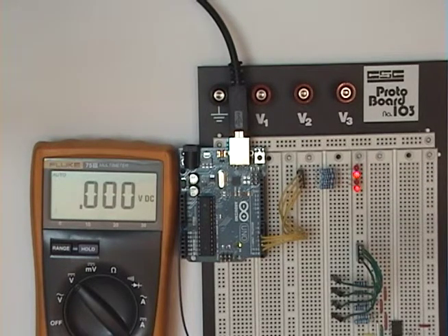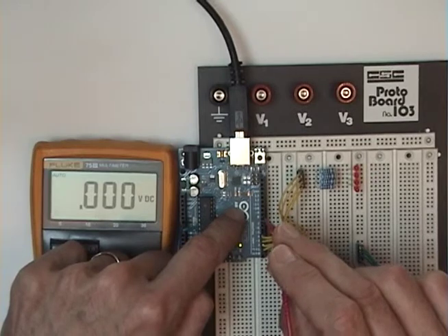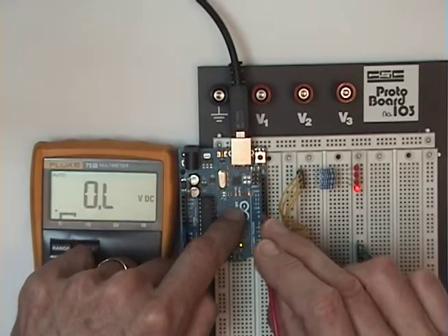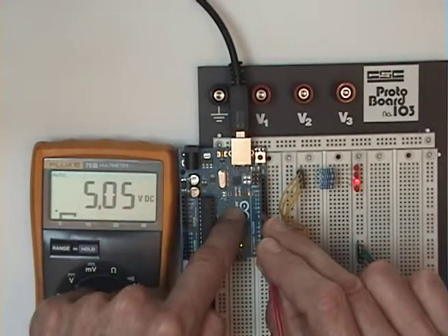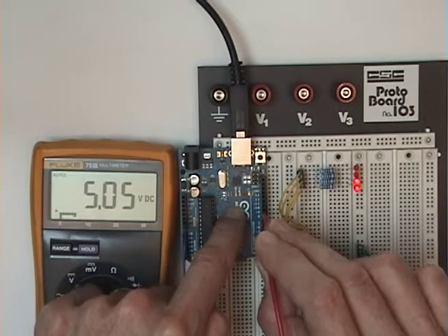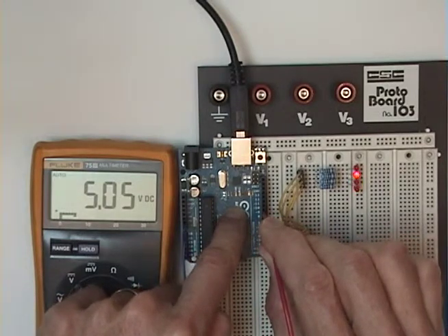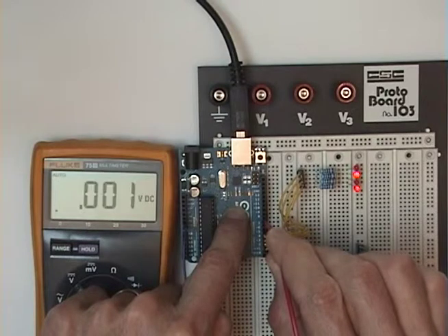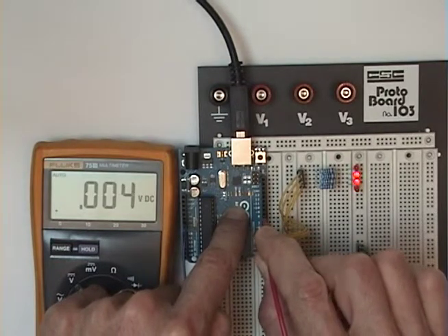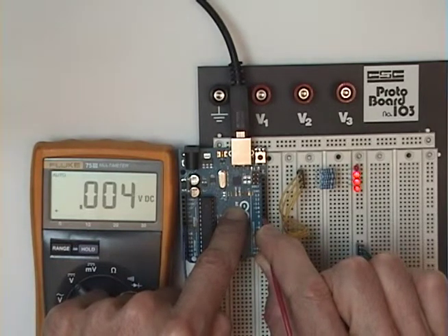In order to do the scaling of the output, I'll need to know what logic 1 is on the Arduino, so let's measure that. I have a constant logic 1 at this output here. I was hoping for a friendlier number, but we can deal with this. While we're at it, let's see what logic 0 is on the Arduino. Remember, I said I was counting on that to be 0. Well, it's not exactly 0, but we'll forge ahead anyway.